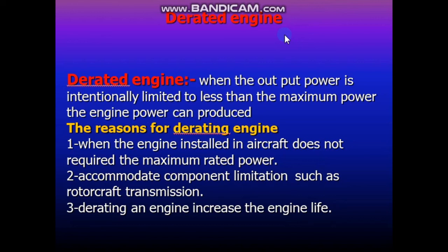The first reason, when the engine installed on an aircraft doesn't require the maximum rated power. The second one, to accommodate component limitations such as rotorcraft transmission, when the component of the aircraft requires the engine not to be at maximum power.